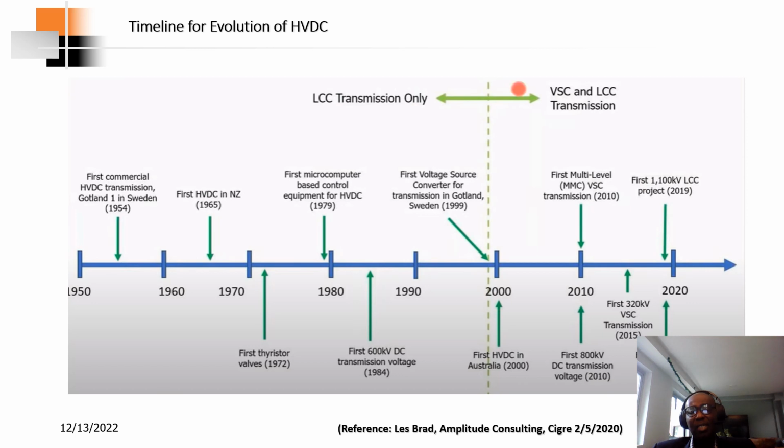And basically there was a limitation on the DC transmission voltage. So around that time it was plus or minus 150 kV. Then it evolved to about 320 kV. For current source converters, basically line commutated converters, technology has helped, and now they're looking at ultra high voltage DC transmission, and they're looking at 1100 kV and about 8,000 kilometers and 10 gigawatts of power being transmitted.